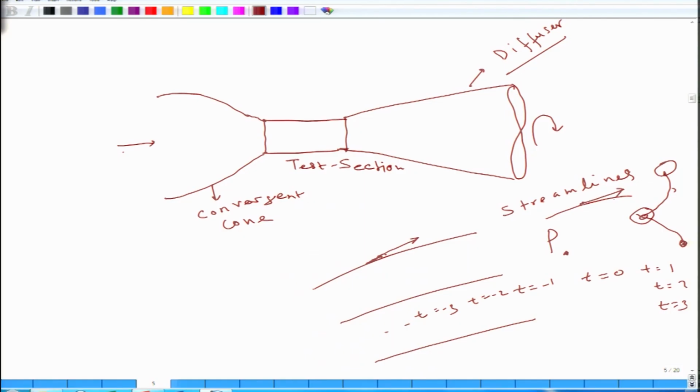However, if only one particle is considered and we follow along with that particle and trace the path covered by that tagged particle, that is called a path line. And the third one, which we said just now: at any point in the flow field, if we draw the line, it is always tangential to the velocity, or vice versa. That is, at the streamline the velocity is always tangential.